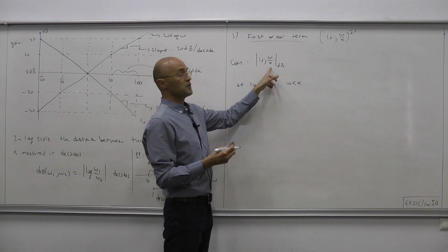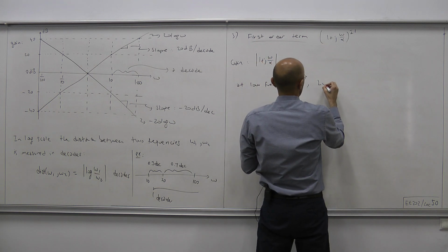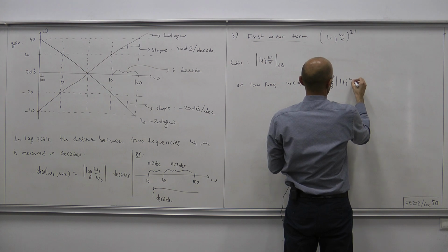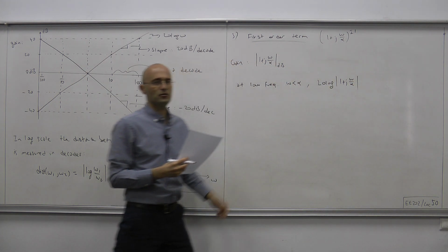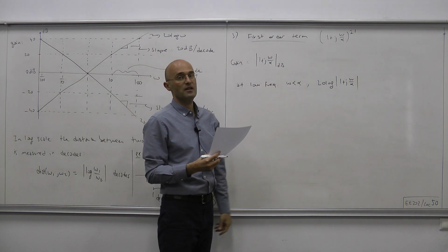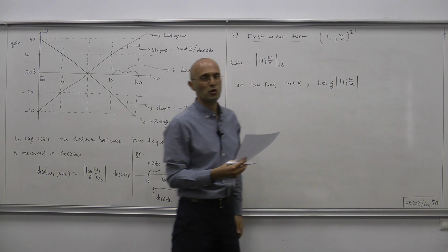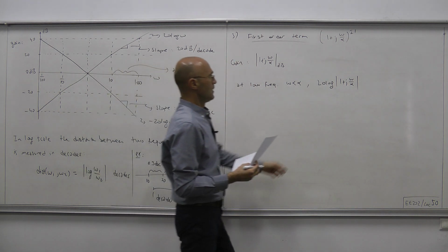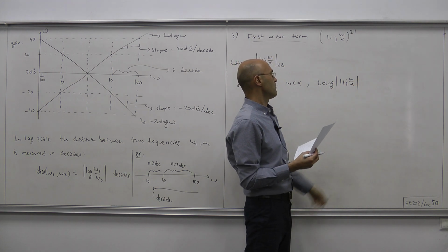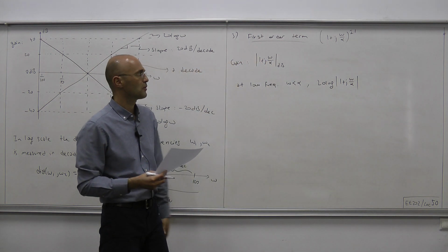Okay, alpha is the term that appears in the denominator here. In decibels, we have 20 log of the magnitude of 1 plus j omega over alpha. Now it turns out, especially if you're expressing things in decibels, that when omega is less than alpha, this can be approximated with simply 1. Okay, so we can ignore the imaginary part if omega is smaller than alpha, and what we have is 20 log 1. Log 1 is 0, therefore 20 times 0 is 0.